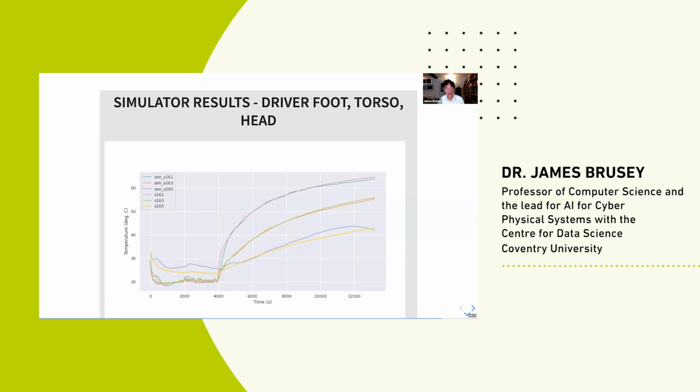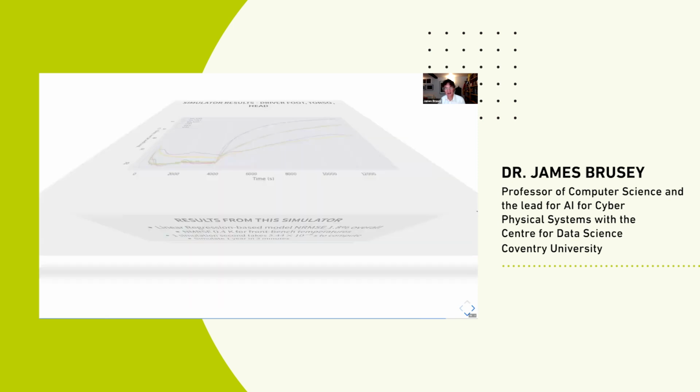In particular, the yellow and blue line, I think, are for the footwell, and you'll notice that's hotter when the car's being air conditioned. That was a little bit high, probably because the air wasn't being directed in the first bit. And then when the car is left to its own devices, it gradually heats up under the solar load that it was under. And of course, the head temperatures, which are the upper part, get quite hot. You can see that it's getting almost to 70 degrees.